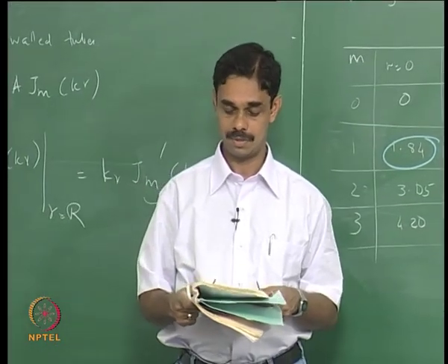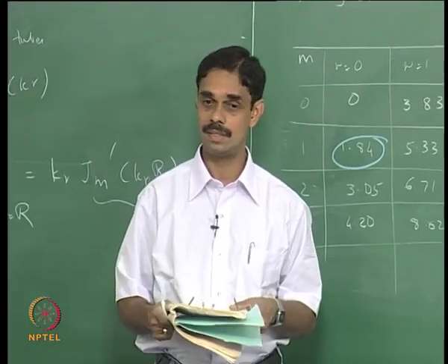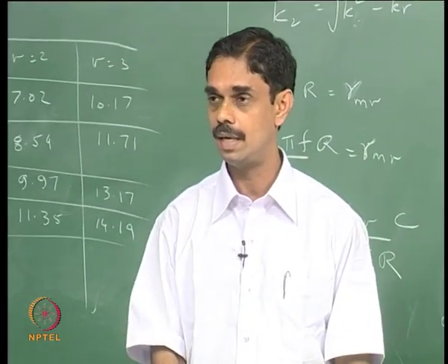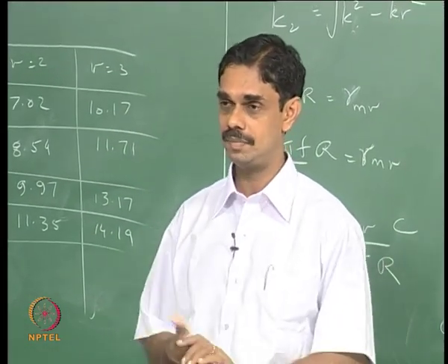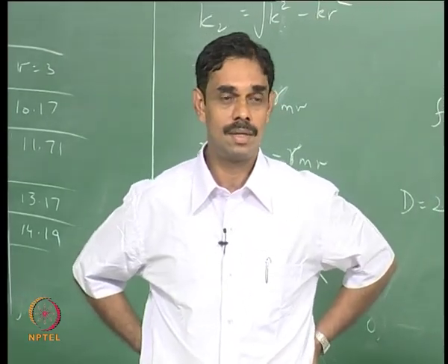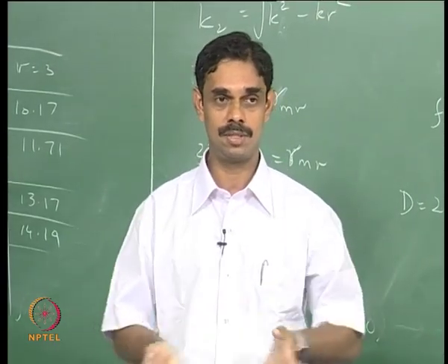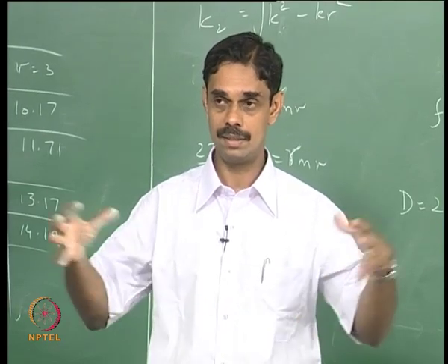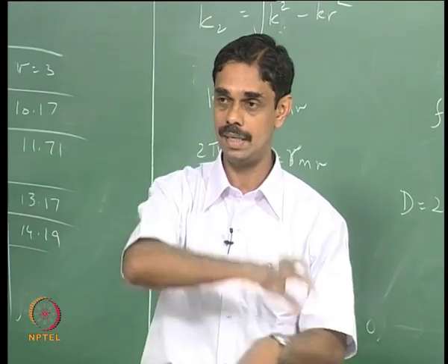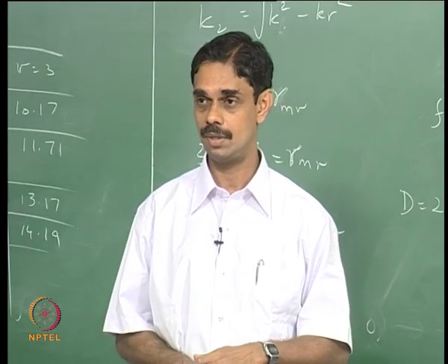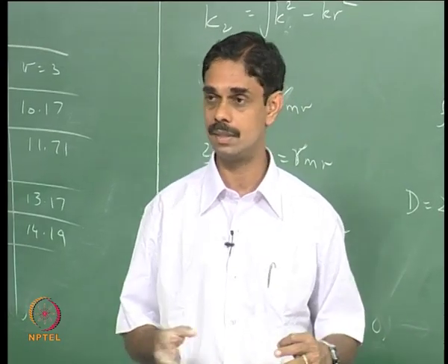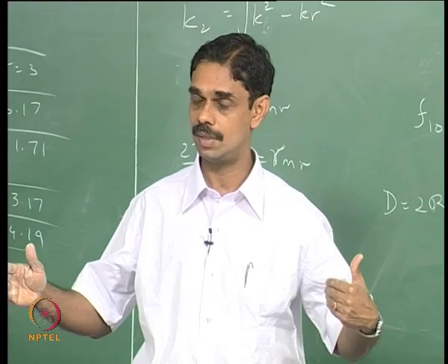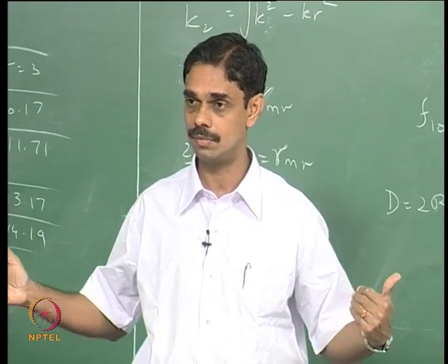So I am going to stop my discussion about the multidimensional acoustic field with this, but in reality there is a lot more to study. I think annular combustors have these annular modes, with this radial kind of structure, as well as rotating modes and so on, but we will not speak much about this in this class. We will concern ourselves with purely axial waves, but I just wanted to give an introduction to this kind of topic.